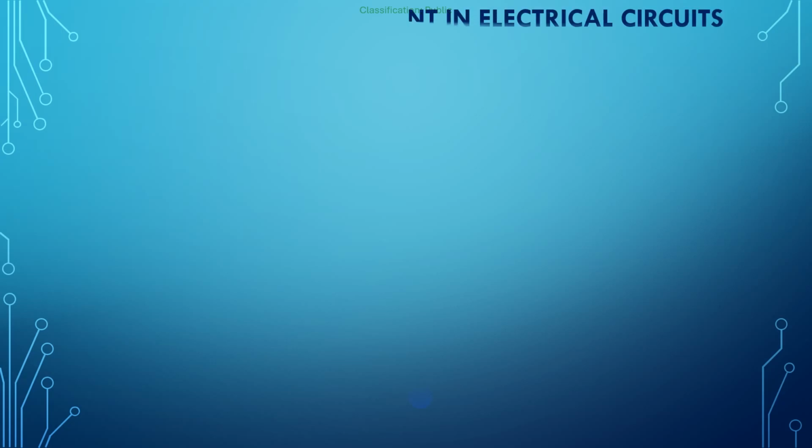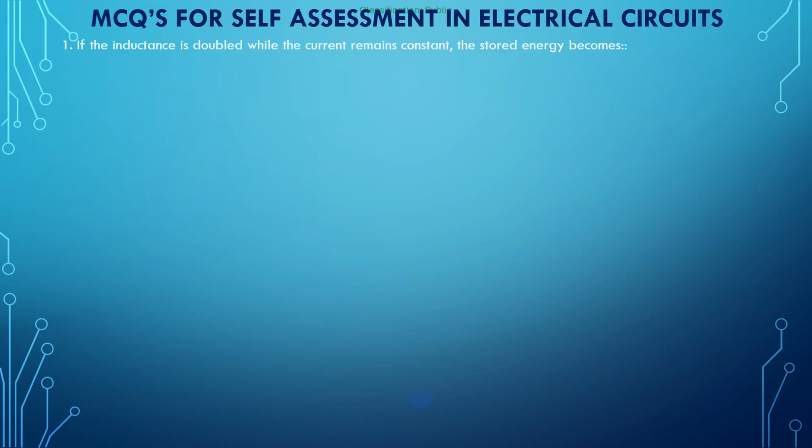Coming to the problems. If the inductance is doubled while the current remains constant, the stored energy becomes? Now it's very, very important. Inductance is doubled while the current remains constant. It is asking energy, so half Li square. Inductance is doubled, current is constant. So what is the energy? The energy is doubled.